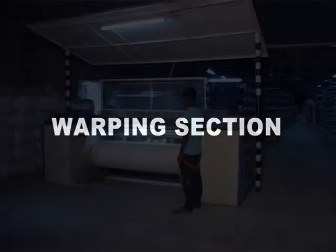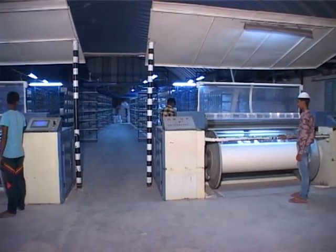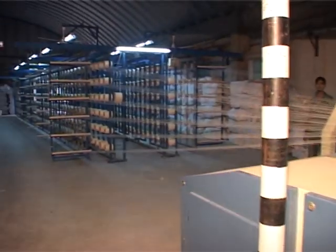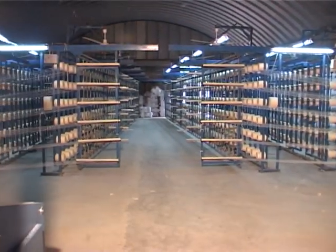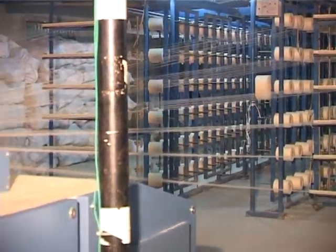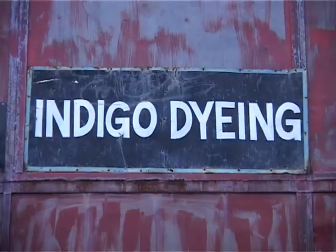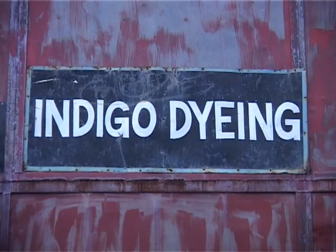It starts with the warping process. In the warping process, the yarn packages in the form of cheese and cones are converted into a bigger package called the spool or the warper's beam. After warping starts the indigo dyeing section. In the indigo dyeing section there are two slasher machines.